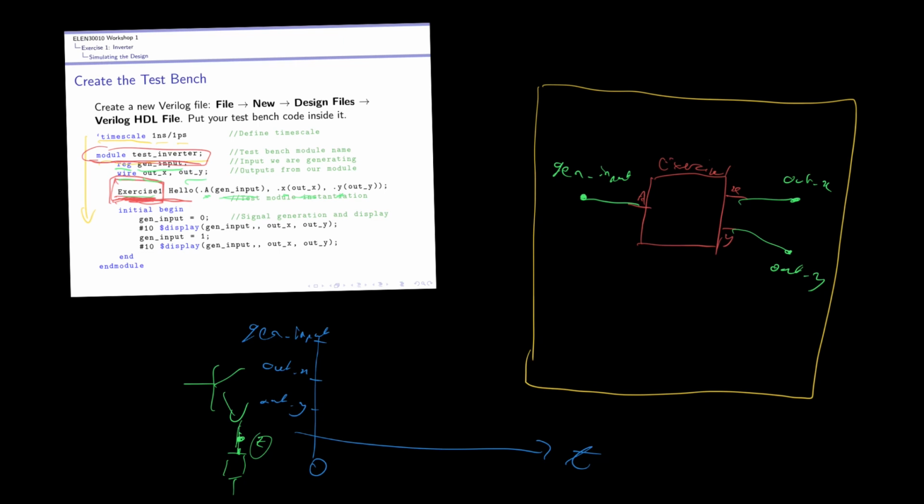Because this is a digital design, each of these nodes is either going to be a 0 or a 1. In physical terms, either 0 volts or 5 volts, for example, but it's either on or off, and so we can display its current state using a diagram like this. What this means is that at time t equals to 0, it's initially a 0. At time t equals to 1, it jumps up to a 1. At time t equals to 2, it jumps back to a 0, and so forth.